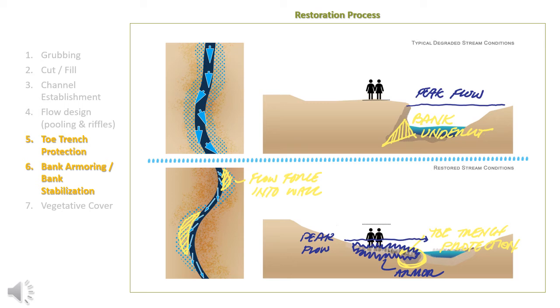This slide focuses in on how you prevent the same issues from re-emerging post-design or post-restoration intervention. One of the things that you see in a lot of the literature on this is really understanding the undercutting of banks, how water is going to move and impact. As we start to manipulate and meander the channel, what we're actually doing is creating different conditions. Some of those places are intentionally going to be the spots where it will naturally want to undercut the bank. We're actually designing the failure point into the system.